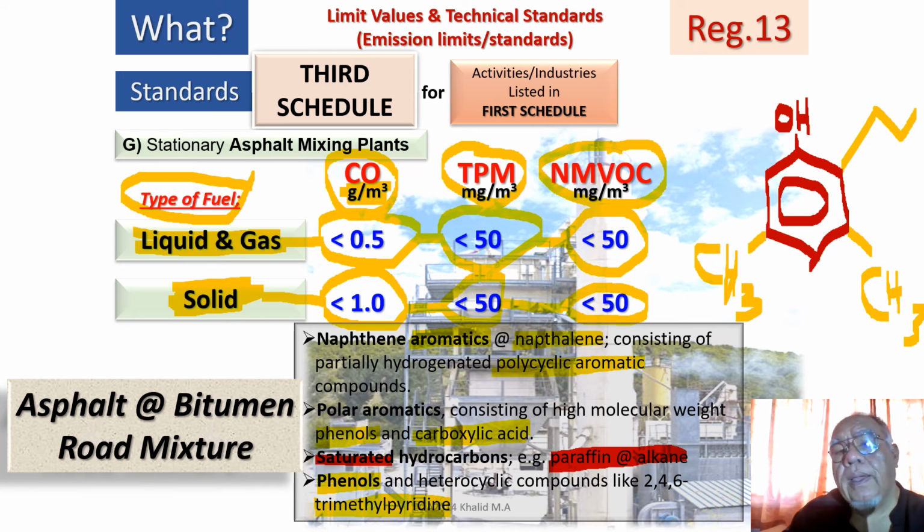So this is the reason why an asphalt plant must be regulated for carbon monoxide and total particulate matter, because total particulate matter has got some surface tension with many other impurities, even heavy metals, even VOCs. But if you look at the VOCs, what I have down here, these are all the VOCs. Naphthalene, pyridine, xylene, toluene, it can be there. At different temperature, it just gets shifted from one compound to another based on temperature, based on pressure.